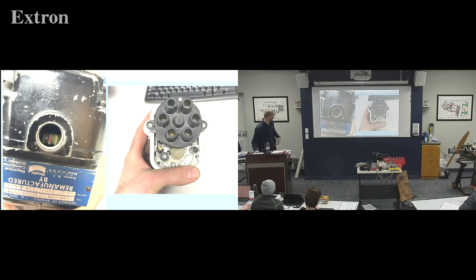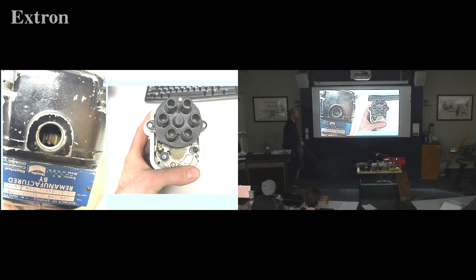All right, here's a picture that shows what I was looking at. Here's the pin installed. See the L here? The R is covered. So if I showed you this picture on an exam, let's say, and I said, I'm getting ready to mount this on an engine, do I have a left or a right-hand turn mag? I've got a right, because I'm in the right hole. The L, I don't have the pin in. I got the pin in the R hole. So it's a right-hand turn mag.